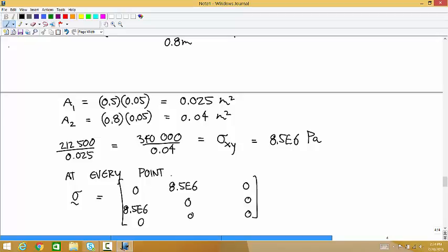And you could compute the eigenvalues and you'd get the principal stresses, and then if you did the 45-degree rotation thing, you'd get some version of this back. This is as big as the shear stresses can be. Those are just the locations of the sigma xy.